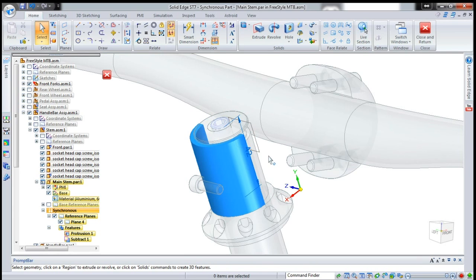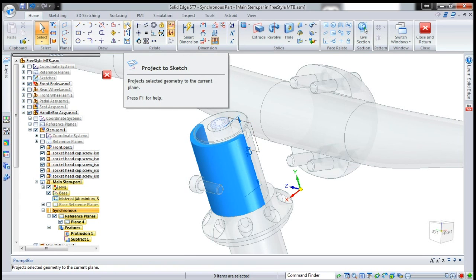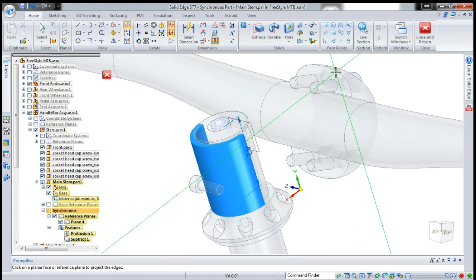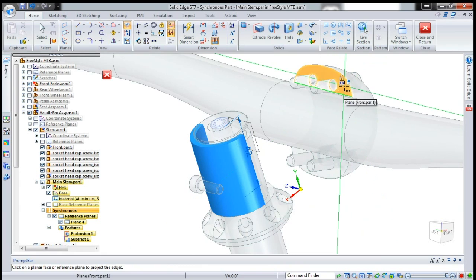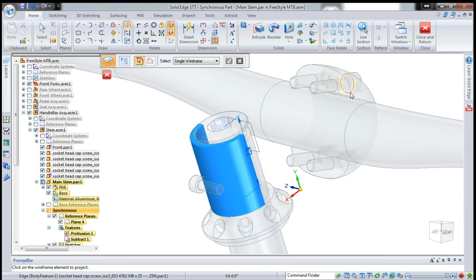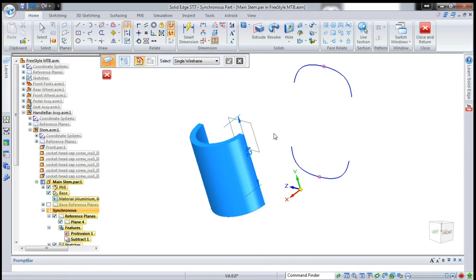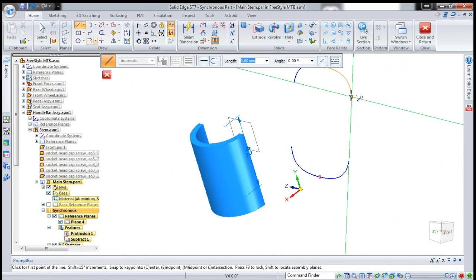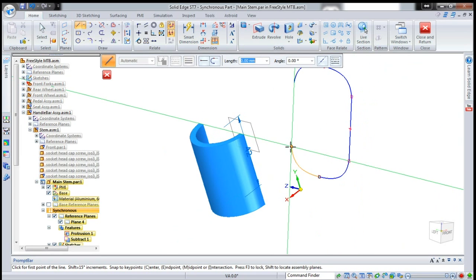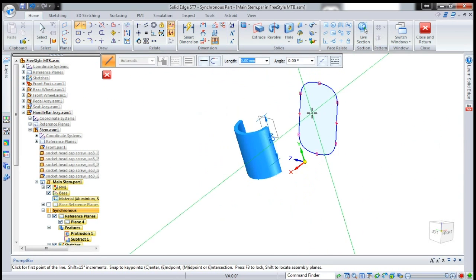So I'm gradually getting the regions and the areas that I want to work with. Now, I want to also grab the outer edges of this component. All I have to do is hold down Shift, and then I can very quickly grab it. Using Quick Pick or just straight selection, I can very quickly get exactly the curves and edges that I want to work with. Now, that's all I need for the moment, so I'll just hide the rest of the assembly, and I'll continue on and fill in the remainder of the details that I want to work with.